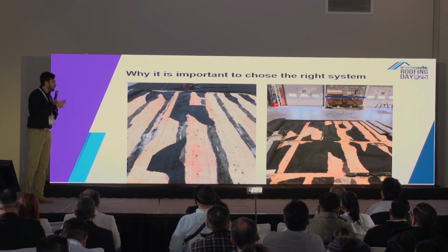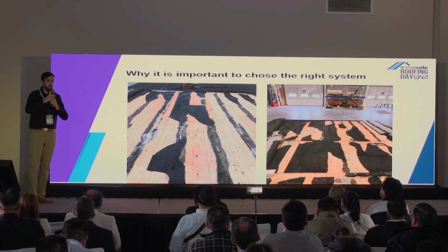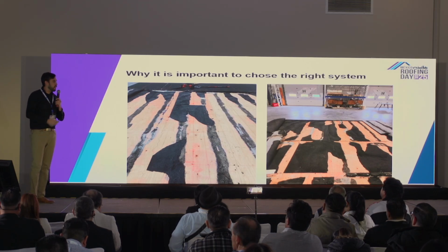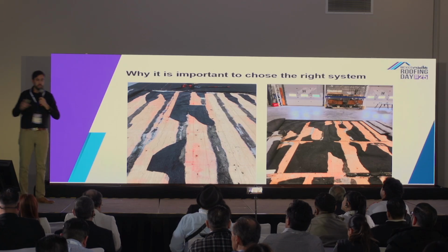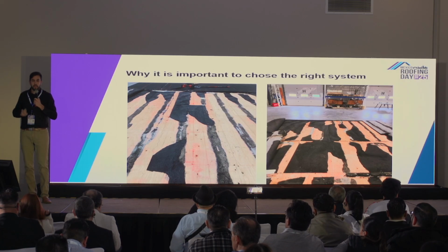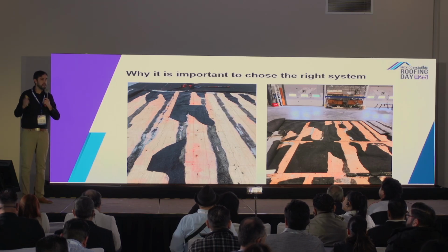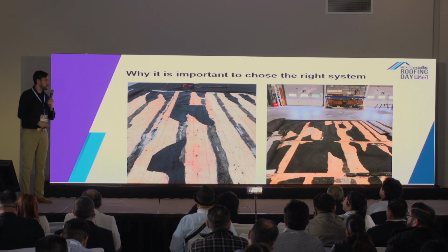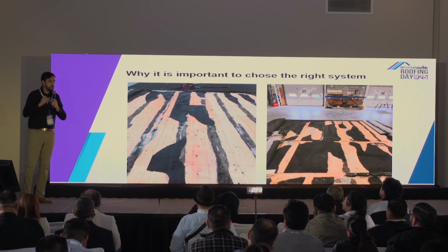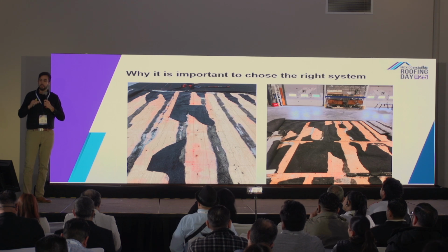So bear in mind that if you see a technical data sheet, for example at FM, with a fastening pattern and so on, this needs to be respected, because otherwise you're not going to meet the resistance that was tested in the labs. Because again, manufacturers are not putting in safety factors, they're pushing the system to the limit.